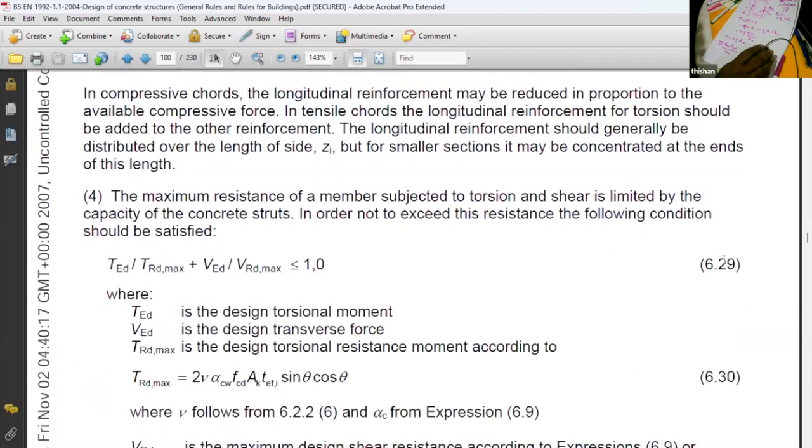These two equations find whether the section is adequate. And if a rectangular section is not adequate, don't increase the depth because you are not going to gain much. Always increase the width, because we know square sections are far better than rectangular sections when it comes to shear. Is that clear, Bandhugal? Yes, sir. That is clear.